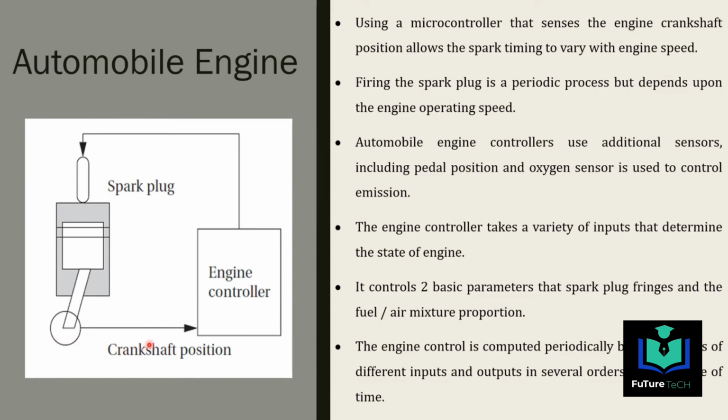Okay, so firing the spark plug is a periodic process. It is not an aperiodic process, because after firing the spark plug, the combustion cycle should start to work. So firing the spark plug is a periodic process but depends upon the engine operating speed. So there are two things that should be noted. As soon as the plug is fired, it should relate to the instant of the engine's crankshaft position.